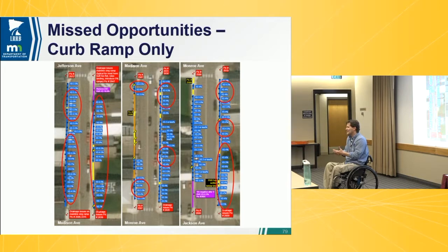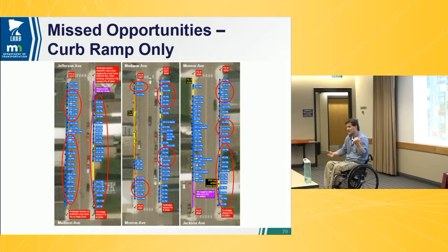And the whole deal is, it's going to be like this for another 15 years. And when we come back in 15 years, it's the exact same fix. It's going in there, raising the curb that we saved the first time, redoing the sidewalks to correct the cross slope, and probably getting rid of their bump outs at that time. So if we're taking this piecemeal type approach, it can really have some detrimental end results. So just curb ramps aren't always enough. You've got to think about how this works as a system and what your goals are to achieve.